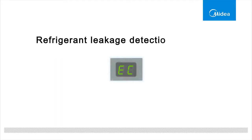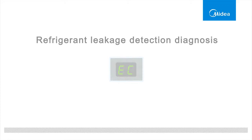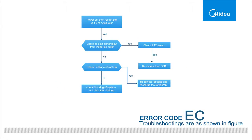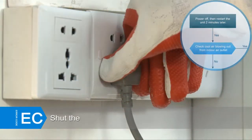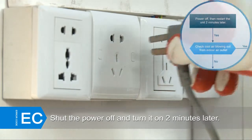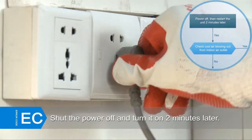When the indoor unit displays EC, that indicates the refrigerant leakage detection error. The failure could be caused by: 1. T2 coil temperature of evaporator error, 2. Indoor main PCB error, 3. Refrigerant system error. Shut the power off and turn it on 2 minutes later.